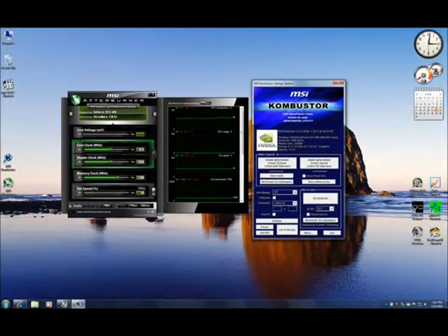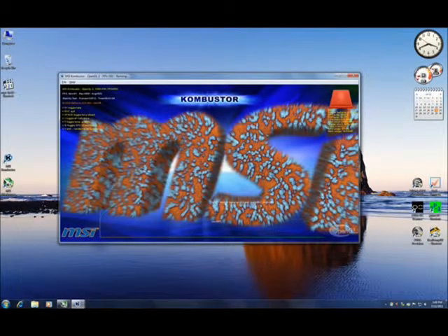Once loaded, on the lower right hand corner you'll see a box labeled Burn In Test with a big button called GPU Burn In. Now, this test will practically push your graphics card to 100% and will quickly bring it to its max temperatures. You can use this program to make sure that your fan settings are adequate during heavy loads. It takes up to 5 minutes or so to reach your graphics card's maximum temperatures.